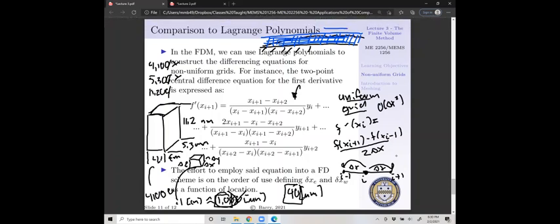So even in fluid problems, having a non-uniform mesh is tremendously important, because you need a really tight mesh in areas where you want to, I always say, capture physics, and people typically take that the wrong way, but where you want to resolve your system of equations and actually determine what's happening. And then in regions where you know it's free stream and it doesn't have too much of an effect, you make that mesh coarse so you don't have too much computation time associated with it. So that's kind of a long-winded answer. Is that decent enough?